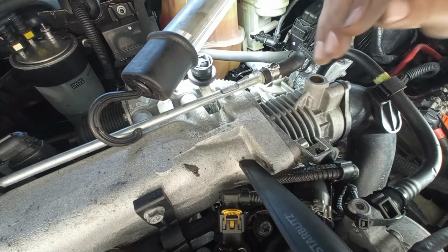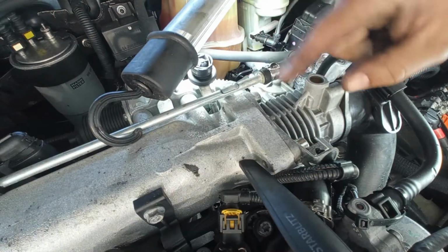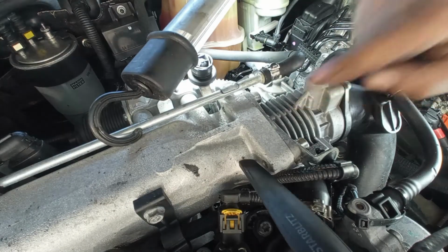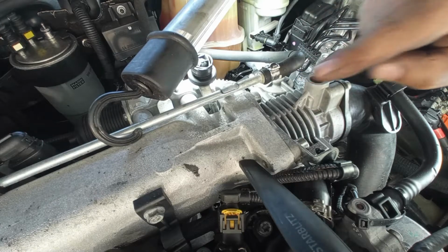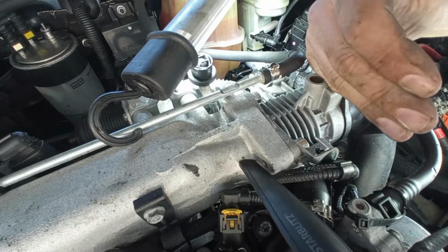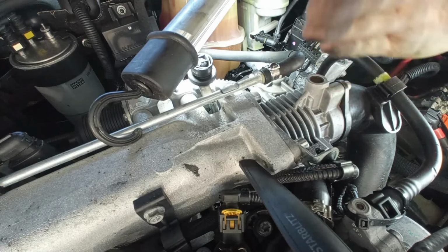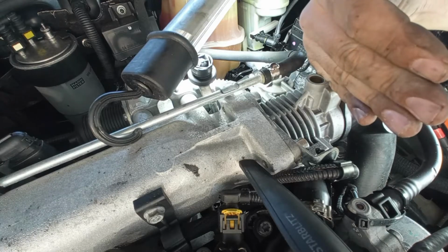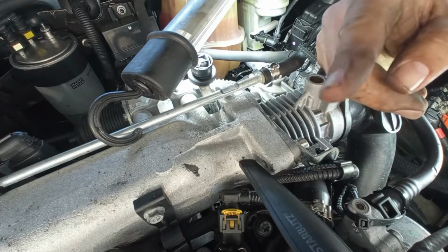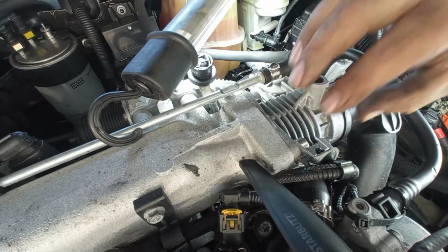Okay, on the deceleration, it closes ever so slightly to help out the EGR gases to pass through. Remember, when having a DPF working, you have to have the EGR working too, okay? The other thing that it does, and is very noticeable, is a smooth shutoff of the engine. As soon as you order the shutoff of the engine, the intake valve shuts off very rapidly. Already showed that on many videos, it is down on the description, and then that way the engine will shut off in a vacuum. That is not happening.